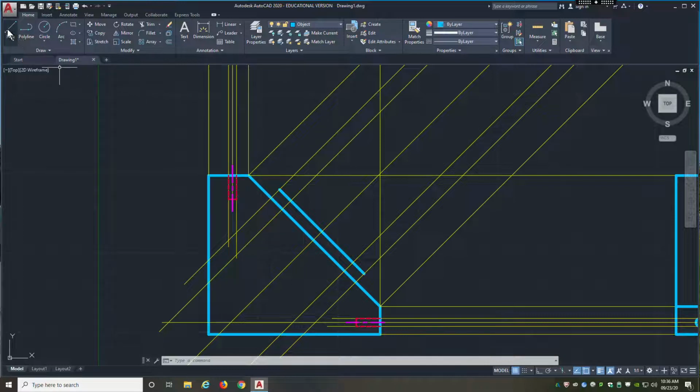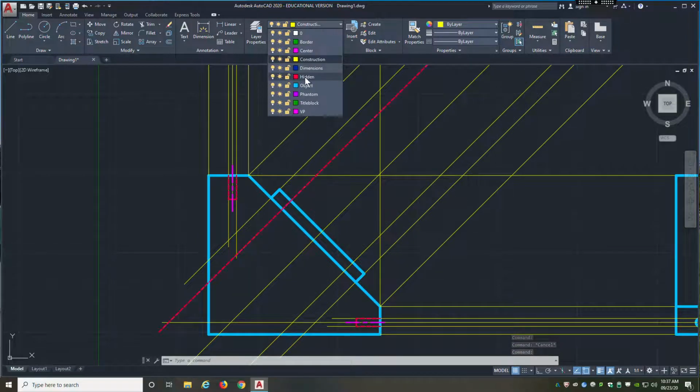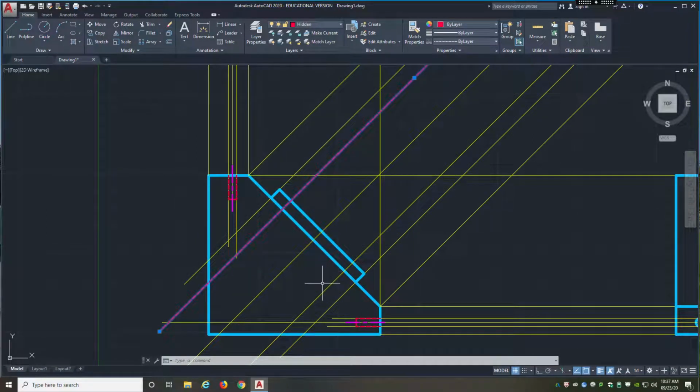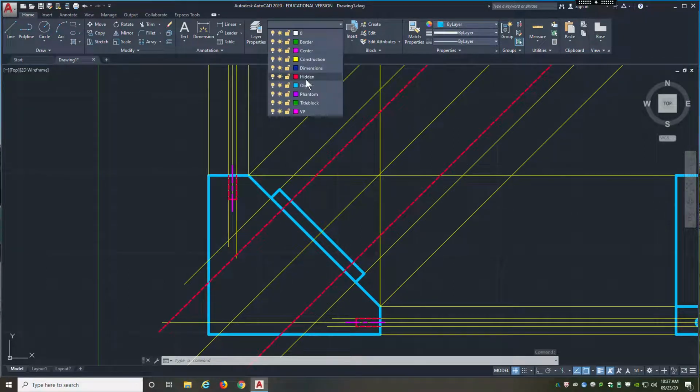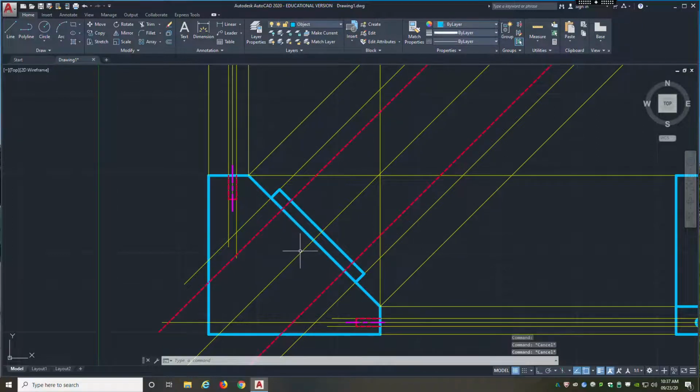All right, so now I've got, switching to my object layer. Now I have points. Make sure that's perpendicular. That looks good. All right, the rest of this is just converting the line types, right? So this line we won't do anything. This second line in, I'm going to change from a construction line to a hidden line, and I'm going to do the same thing with that one.